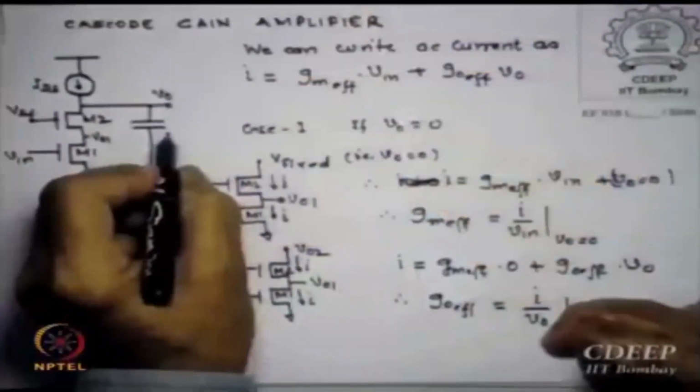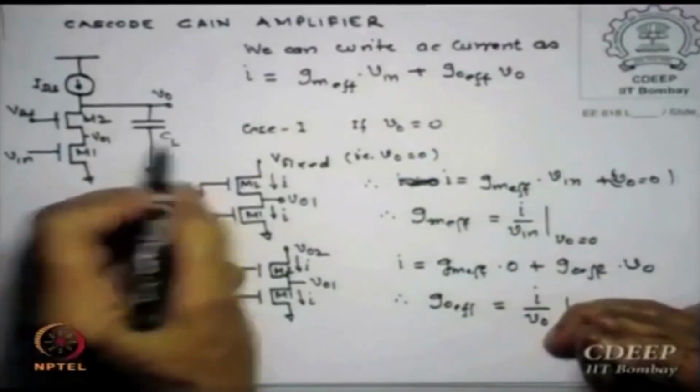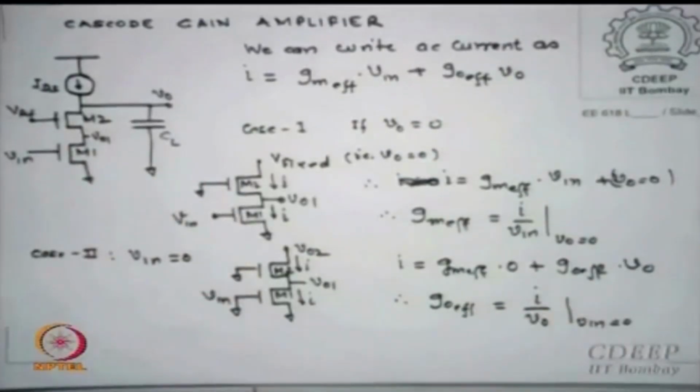So to say it, let me put it, this is a capacitance C which is the load capacitance. This amplifier is driving a load capacitance. This load capacitance is such that all other capacitances can be neglected except the output capacitance, which is taken as the net load capacitance. Is that clear? Remember, bandwidth can be a function of input capacitances, series capacitances and output capacitance. I say this gives you what we call the dominant pole for the case of solving.